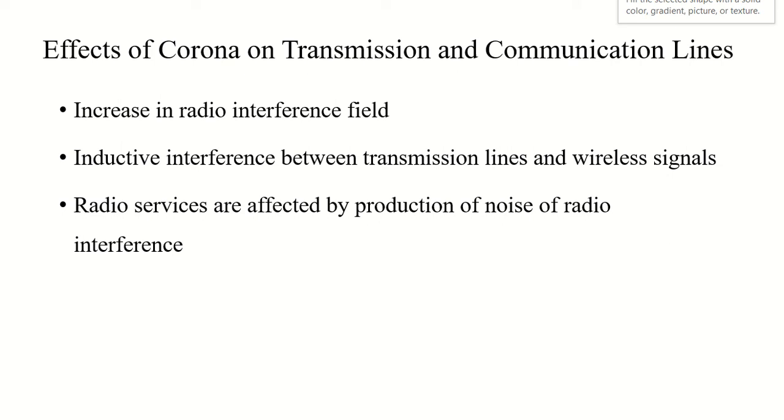and this is because of the current pulse generated by corona discharge. So which other things are also getting affected? There will be amplitude modulated broadcasting signals, power line carriers, aviation, marine ship calls. All these things, and even other similar services, are badly disrupted because of the corona effect. This corona discharge will also affect kilometers of lines on both sides.